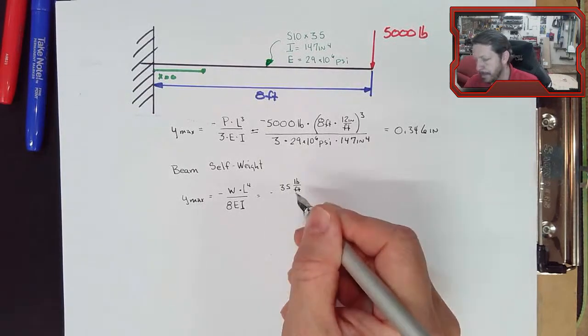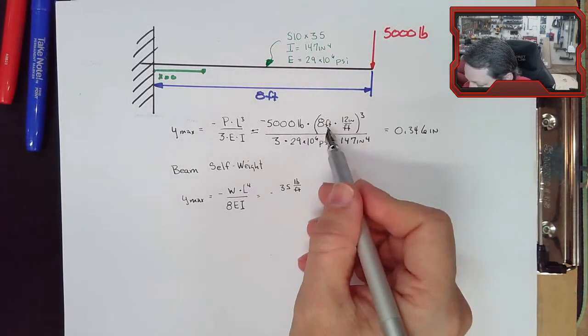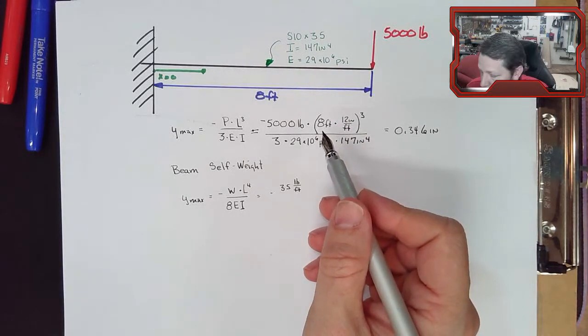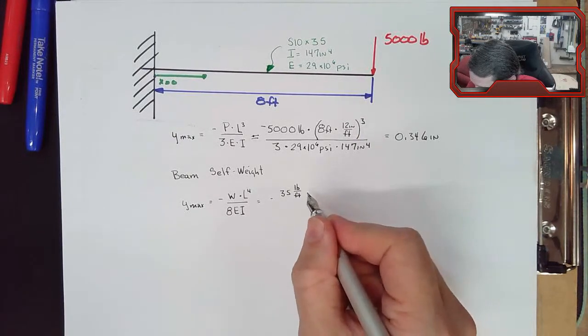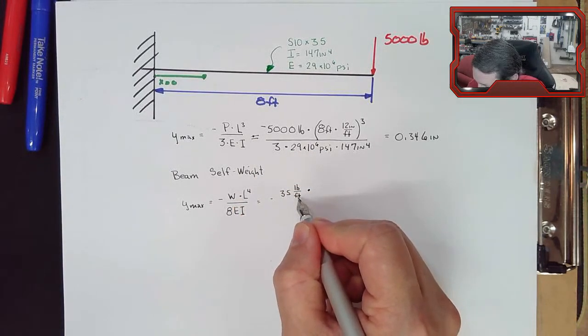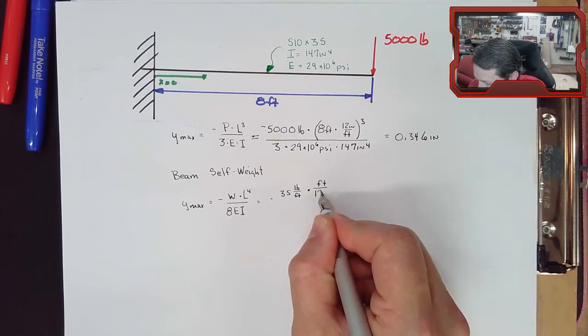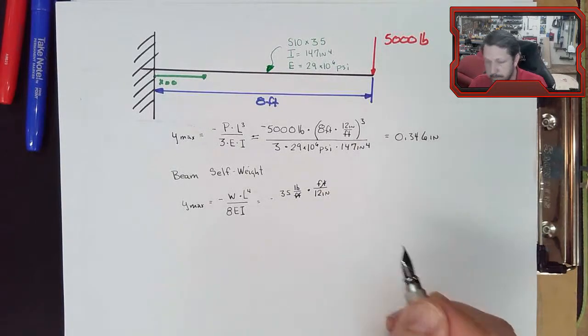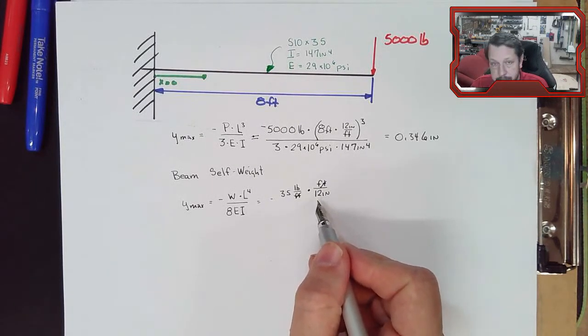And here's where I wanted to just point out and make sure that we did right. Because MathCAD would just do it without us even realizing it. So we've been converting feet to inches quite a bit in a lot of different problems, and we just multiply times 12 is really all we do. But this is pounds per foot. So you do have to be careful, and this is one reason to write your units out carefully. To cancel out these feet, I need feet in the numerator of my conversion factor, which makes me divide by 12. So make sure you don't just automatically multiply times 12 because you need to convert something with feet in it. And here you need to divide by 12.